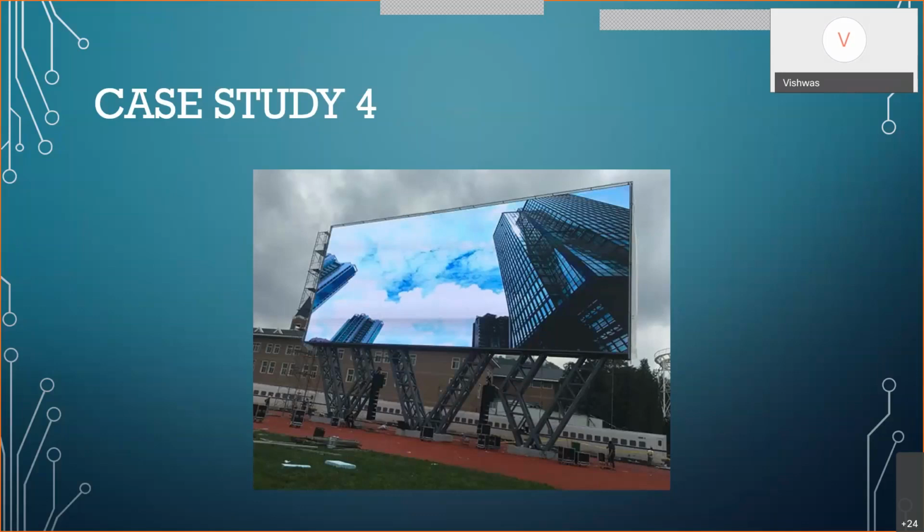technology of a huge, large panel display, and you're right, it is LED. A projector might not be the case, because in broad daylight you will not be able to see the projection on the screen properly. You'll need such a bright light, so it's a waste of energy, and the projector lamp itself emits a lot of heat, so it's not efficient to have such a big screen. So LED is right. The whole display is made up of small LED matrices which are easily replaceable. You can put LED matrices in a number of rows and columns, and you'll have a huge display.